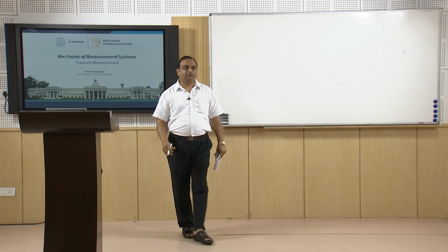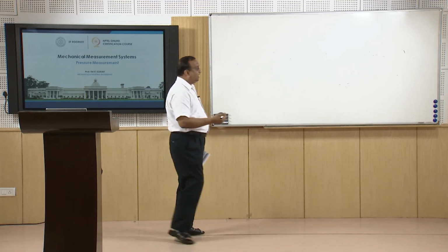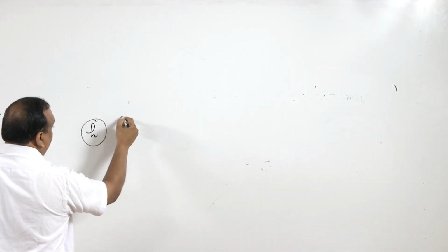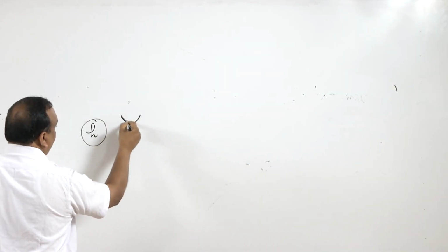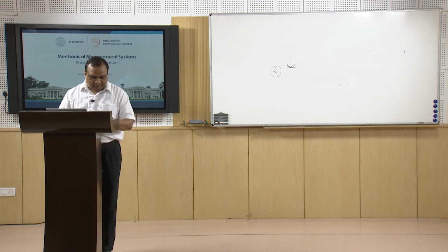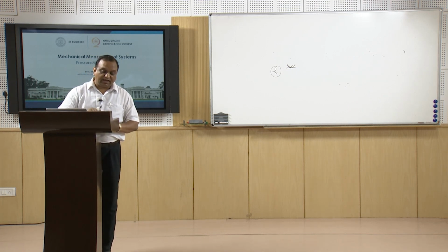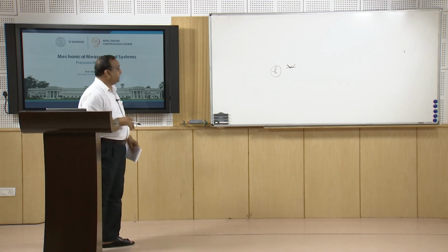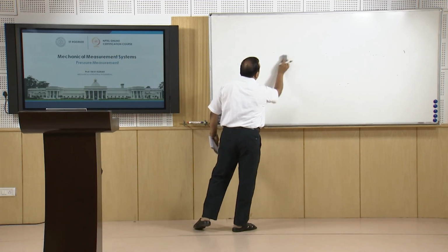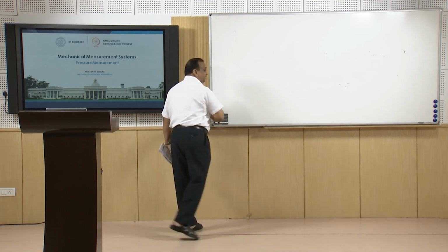And the scope of error in the U-tube manometer is, first, the capillary effect. Certain height we get through capillary effect also. Another is reading the manometer. One should correctly read the meniscus of the height of the column, otherwise there are chances of error. And lastly, gravity and temperature also have a bearing on the measurement by the manometer. So they have to be taken into account.